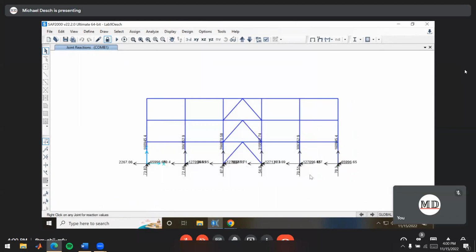So those are all of our reactions for those fixed supports in this plane here. And you see we've got our reactions as forces as well as moments here. So the double-headed arrows are moments about the axes they're rotating, using the right-hand curl rule convention. Like this one is pointed up, so with the right hand, it's going to be curling this way. What's happening? We didn't get the same value. Uh-oh.